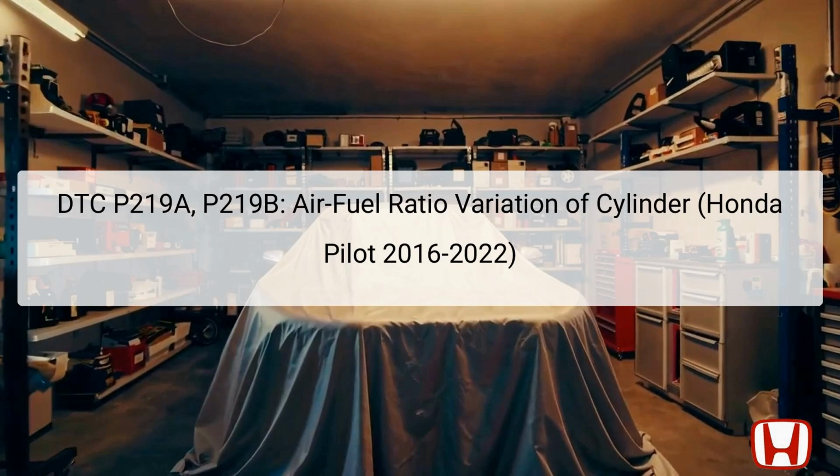The DTC codes P219A and P219B specifically indicate an air-fuel ratio variation for cylinders in a Honda Pilot manufactured between 2016 and 2022. DTC P219A pertains to Bank 1, which typically contains cylinders number 1, 2, and 3, while DTC P219B refers to Bank 2, usually encompassing cylinders number 4, 5, and 6.